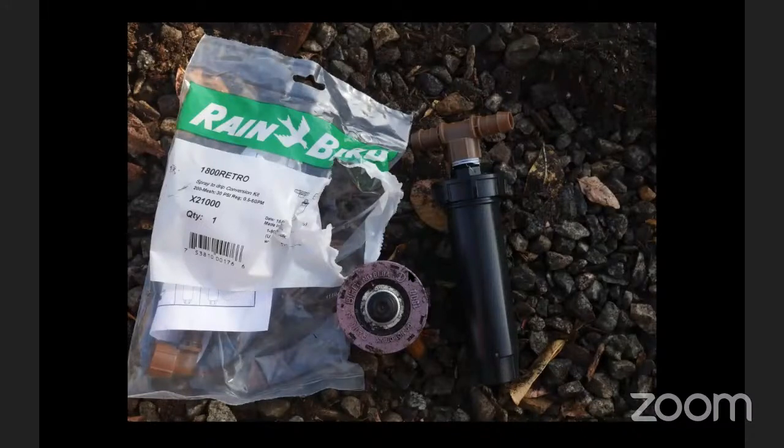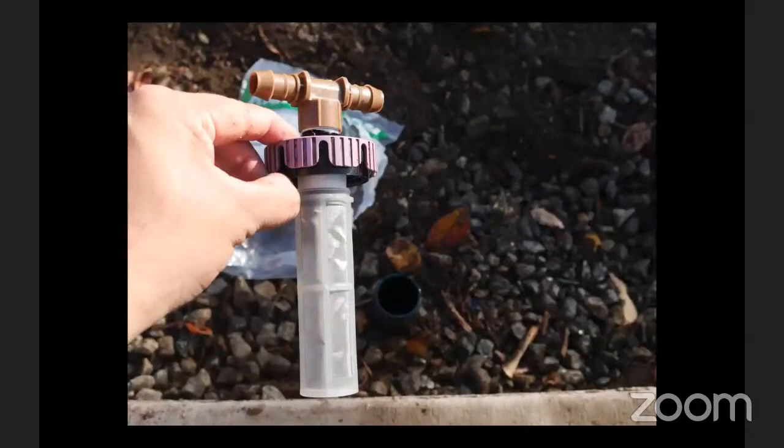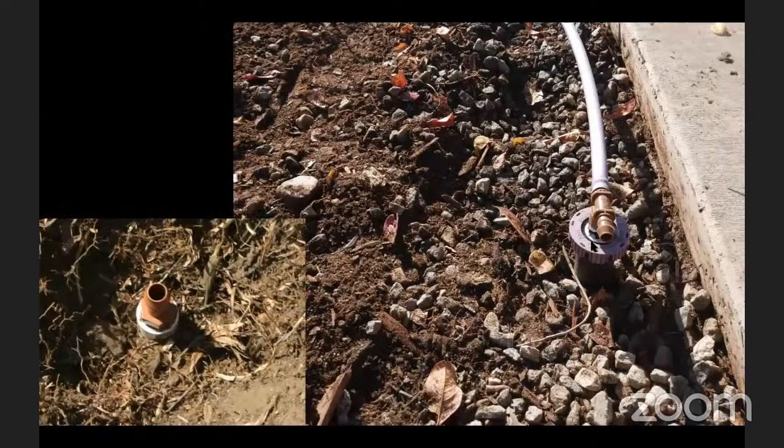You will not be at home. So your drip line is going to be brown, and this is just a recycled water indicator. And so here's what we had. We pulled it out here. These were 12-inch pop-up sprinklers, so your piece will not be that long, but we just unscrewed that. And then here is our adapter kit. Because we had the Rainbird brand sprinkler in here, we were just able to take the guts out, screw that onto the body, and then we could connect and start irrigating from there.